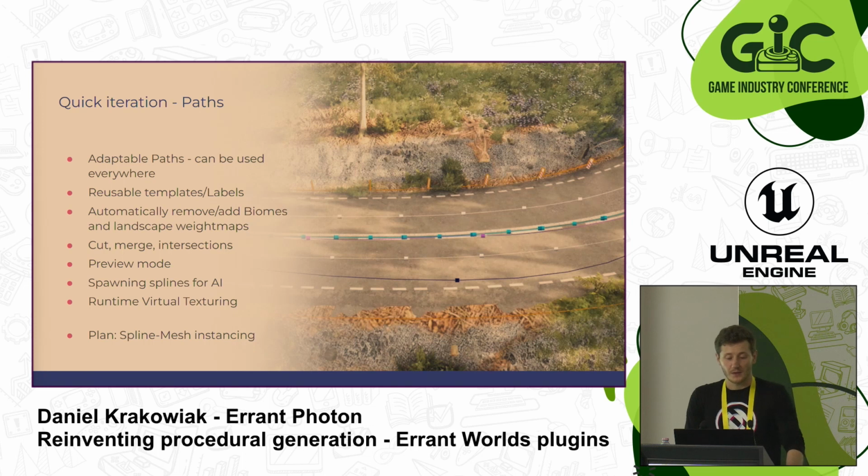We also discovered that using runtime virtual texturing is great for roads, because roads don't have a big surface, and they extend along a camera, which is really useful for loading the textures and streaming them in. And you very often have lots of decals in roads. So with runtime virtual texturing, you render all these decals into the virtual texture, and then you're only using this texture to render the actual road, which is a huge saving.